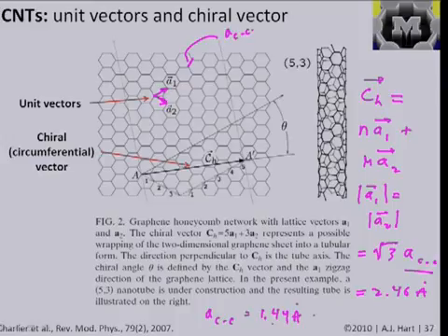Yeah, so the periodic table, which we'll see at the end, has a nice summary of all these things. The ACC is 1.42 in graphite and about 1.44 in a carbon nanotube, because you have this surface effect, because you have the stress necessary to wrap it up when you create a tube. The bond distance actually depends on the diameter of the tube slightly, and we'll see that later in terms of mechanical properties, but it's just like we saw for gold.